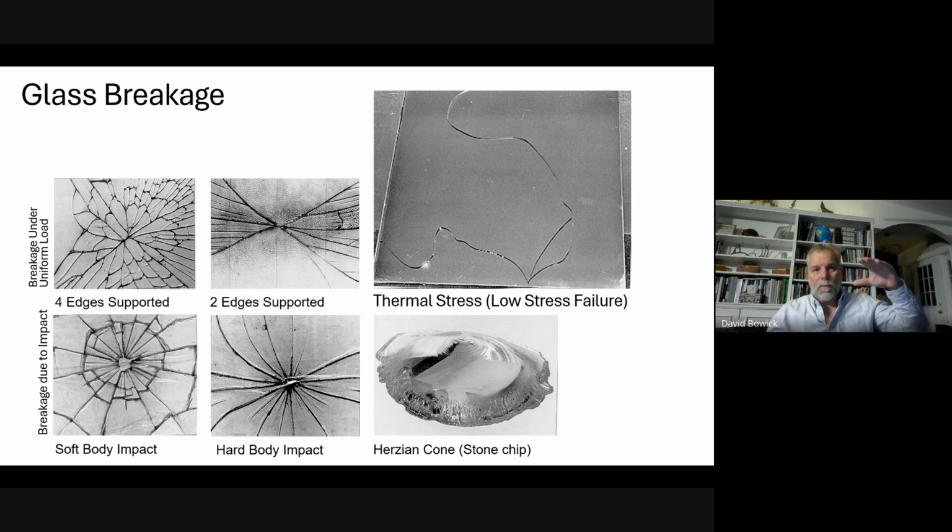So the top of the window was shaded by the overhang, and below that it's exposed to the bright sun. And so the bottom warms up, the top stays cold, and we wind up with a crack migrating down from just under the roof, migrating into the field.